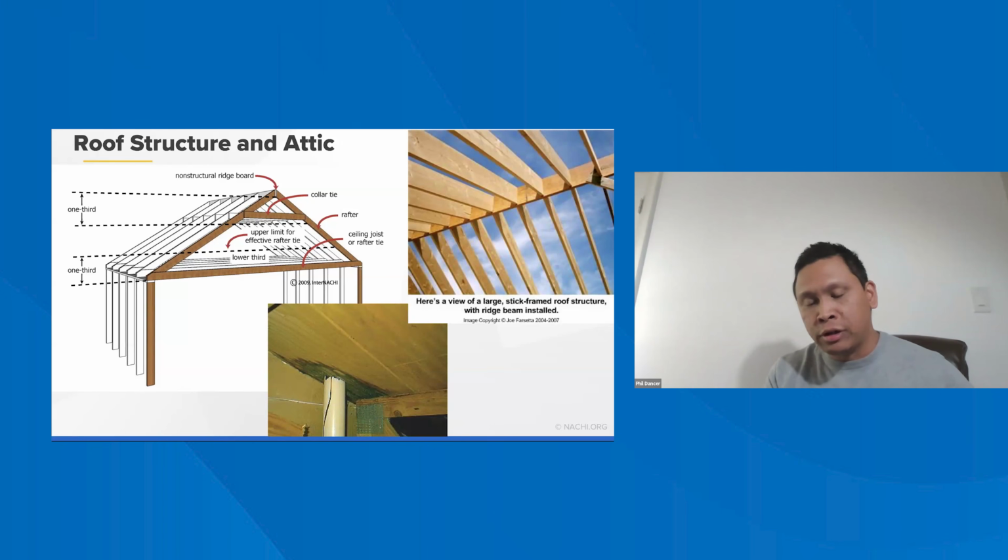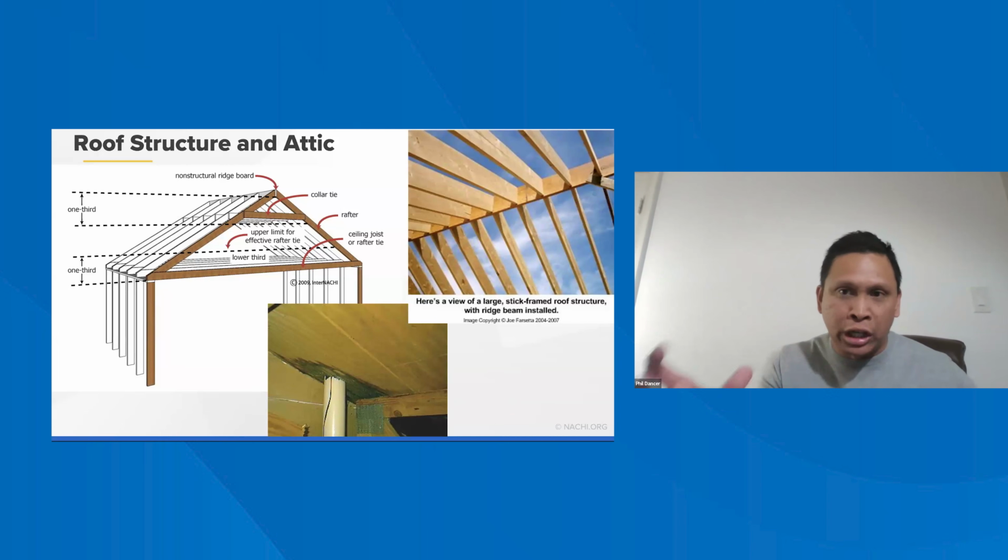So the big thing is that seasonal truss uplift, from a new construction standpoint, is an undesirable condition because it's essentially creating what the builder would just default describe as settlement cracking in between the ceiling and wall. Unless the builder did a really good job at trying to control the actual truss uplift condition, then repairing the drywall in the ceiling and wall connection, it's always going to come back looking like settlement cracking.